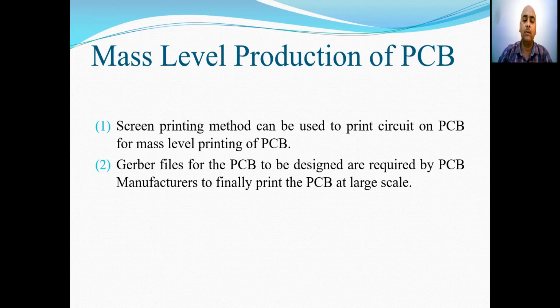The Gerber files for the PCB to be designed are required by PCB manufacturer to finally print the PCB at large scale. The Gerber files for the circuit are generated from the board layout of PCB, which has been designed by some CAD tool. So this was the complete process for printing the PCB that we wanted to discuss in this class. So this is all that we want to discuss in this class.